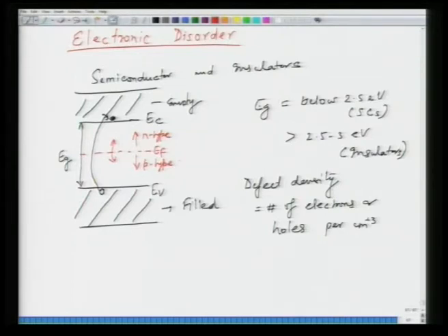And when you start putting in impurities, then you also introduce something called donor or acceptor levels. So this would be your acceptor level, which means it will accept electrons from the valence band, giving rise to a large hole density in the valence band, and this will donate its extra electrons. So this is typically, for example, in silicon, aluminum would be an acceptor, because aluminum is a +3 atom.